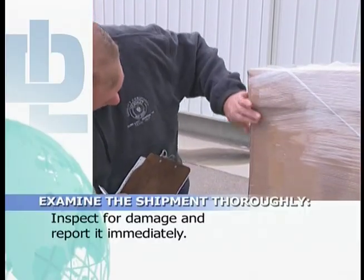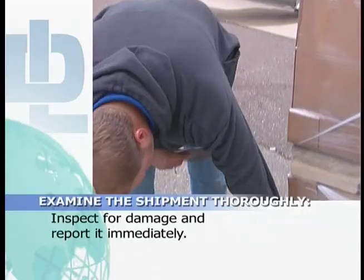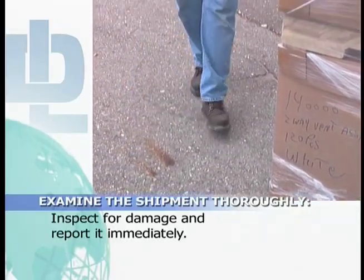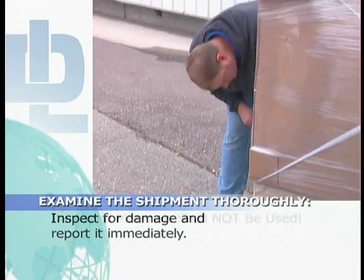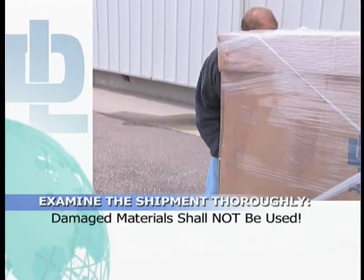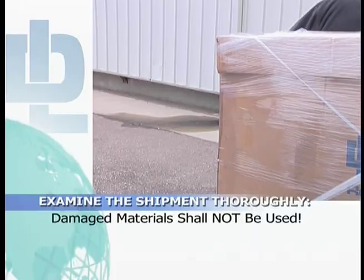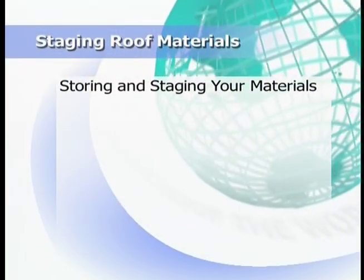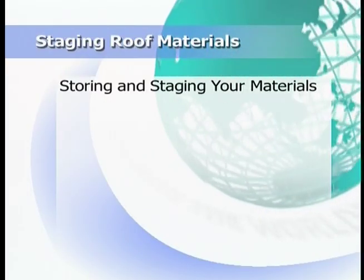The freight agent or receiving clerk must note all damaged materials and/or shortages on the freight bill. Immediately report to the carrier any concealed damage. Materials damaged in shipping, handling, or storage shall not be used at any time. After completing a thorough inspection, it's time to store and stage your materials.